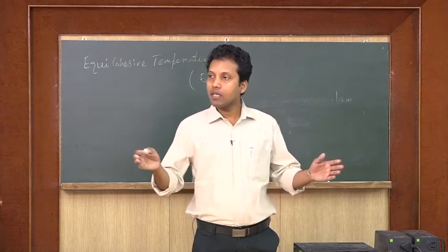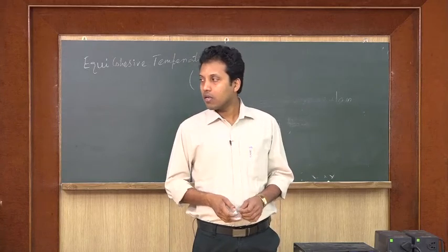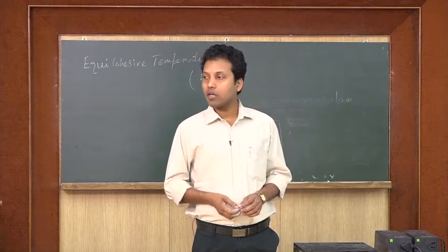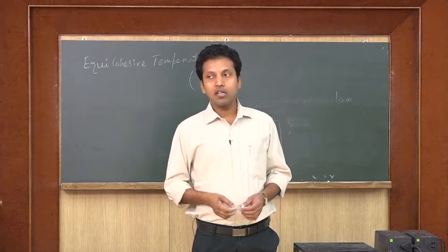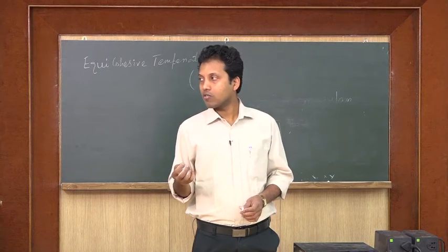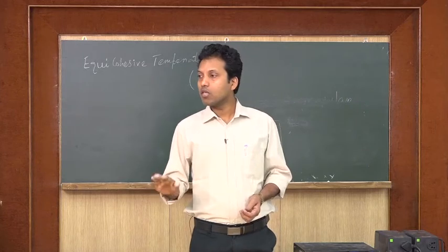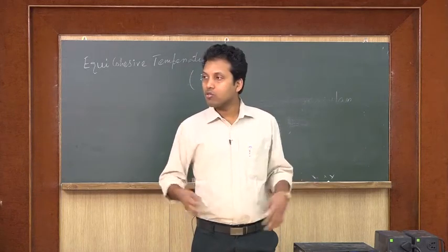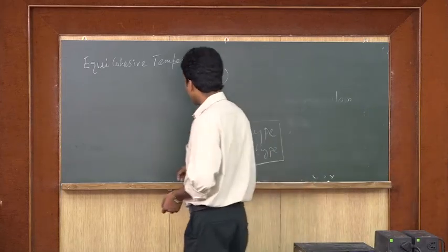If I have big grains, working above equicohesive temperature, then easy crack propagation may not take place. So, above equicohesive temperature, small grained material is weaker compared to large grains, which is opposite to the case when we are working below the equicohesive temperature, where we want to reduce the grain size to increase the strength of a material. This phenomenon you must understand.